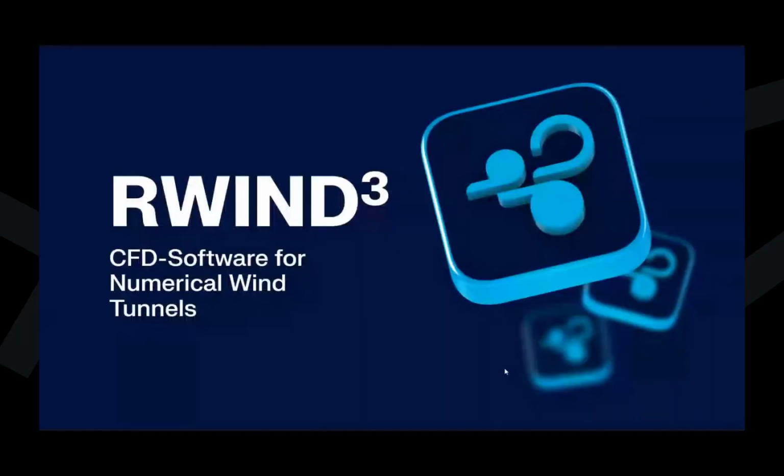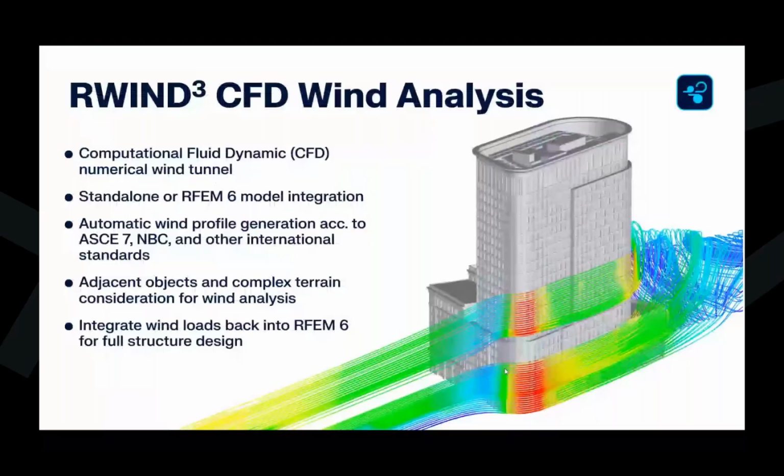Moving on now to RWIND 3. So this is our CFD wind analysis program where we utilize a numerical wind tunnel. So for those of you not familiar with CFD, this is computational fluid dynamic analysis, where essentially we take our structure, we put it into this numerical wind tunnel to determine what these wind pressures are. Now, RWIND can certainly be used as a standalone. We have architects, for example, taking advantage of this. It's not necessarily just for the structural engineer where you could import in an IFC file, because all that we need is the geometry here to determine what these wind pressures are.